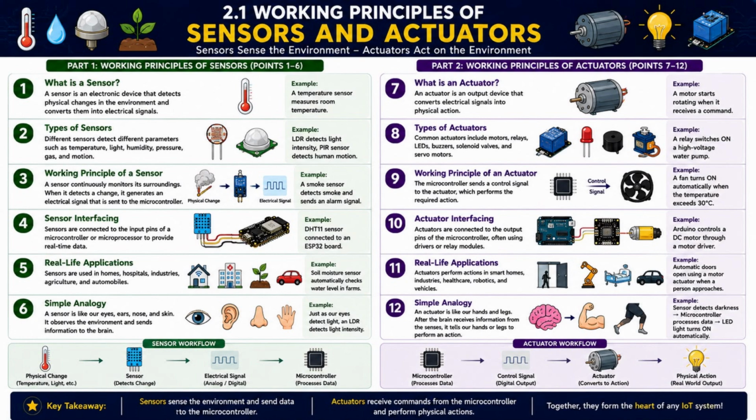How to connect an actuator to the microcontroller? That is interfacing. We want to know. Actuators are connected to the output pins of the microcontroller, often using drivers. Okay, that you should remember. Can you tell one example of an actuator? Arduino controls a DC motor through a motor driver. That is very important to remember.